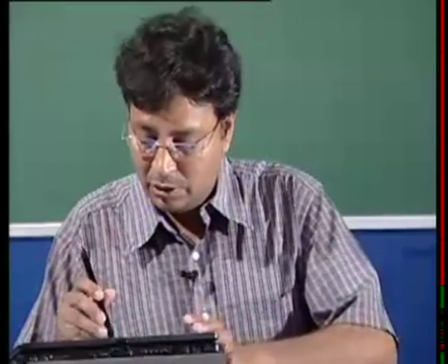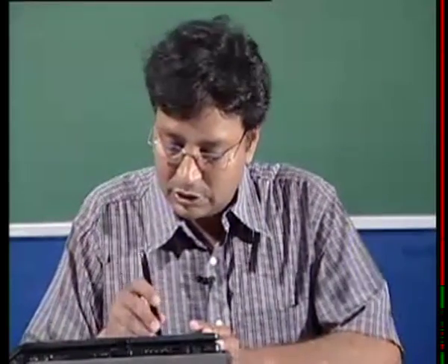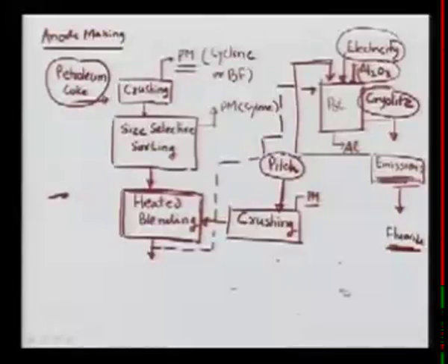So I'll remove this stuff here. You see, in this process we are not baking the anode previously; the paste itself, as you see here in the dash form, is sent to the pot.